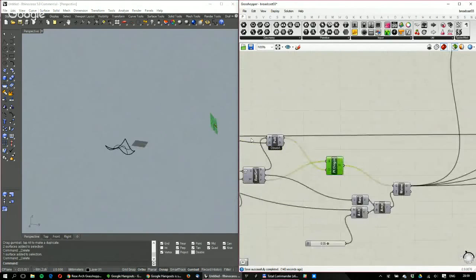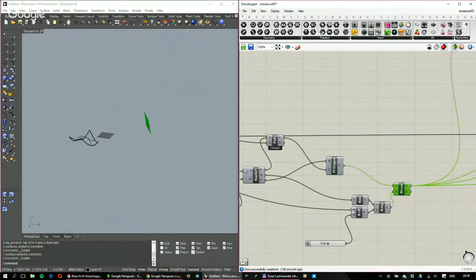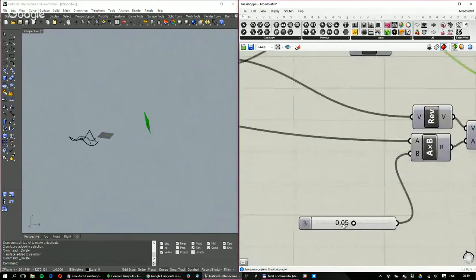Then I pull the point to the geometry. I will change the origin of the plane. So I actually pull the plane there. That's my cutting plane. But I also move it slightly inwards. And maybe this is even too much. I should move it slightly less inwards because I'm chopping off whatever is outside. So that if the outermost point is a tip of the geometry, we don't want the geometry to grow from the tip.